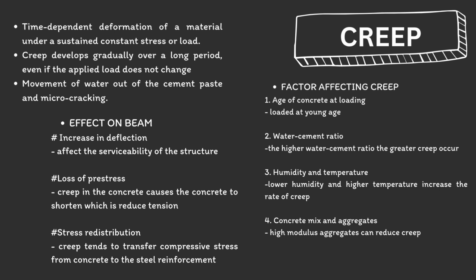I'm Macquarie Alcini Anak Matthias, and I will explain about creep in concrete. Creep is time-dependent deformation of a material under sustained constant stress or load. Creep occurs over a long period, even if the applied load does not change. It is because of the movement of water out of the cement phase and also micro-cracking.